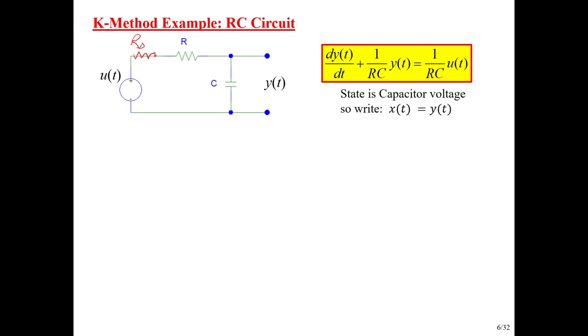Now, whether I have that there or not, remember those two things combine in series. So I could just leave that out and make sure that I bump that up by whatever the output resistance of the driving stage is. So no harm there, no foul. But the driven stage would give an input impedance, which we'll assume is just a resistance in parallel with that capacitor. Now, if that's big enough, we can just ignore it.